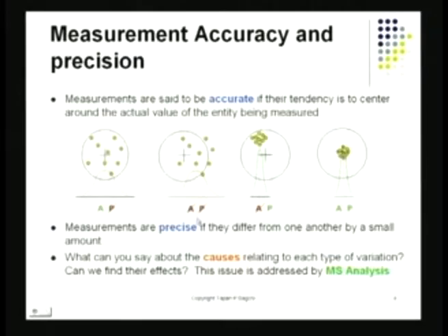This is the situation when I say that the system here lacks accuracy. It is not an accurate system. Also look at the wide spread, which is shown by this little bell curve here, which shows the distribution of all these shots. And again I say there's a wide distribution here that actually implies that this system also lacks precision.